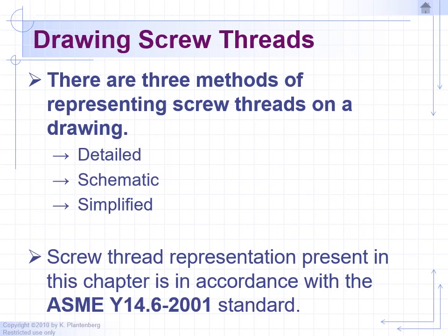Okay, so how do we draw screw threads on a drawing? There are three methods of representing screw threads on a drawing: the detailed, the schematic, and the simplified. Screw thread representation presented in this chapter is in accordance with the ASME Y14.6 2001 standard.